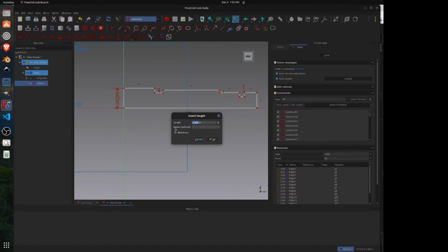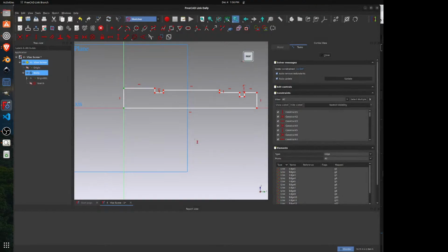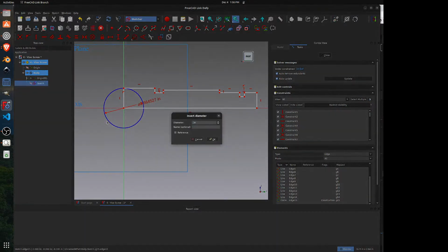You can do it this way. I just don't think it's a robust way of doing it, because I think in diameters instead of radiuses. I don't go by 3/8 radius round bar when I want 3/4 inch diameter round bar. So what I like to do when I do revolves is I like to draw a circle in a convenient location, and then I convert this to a construction circle, and then that allows me to apply a diameter to that of 0.75 inches.